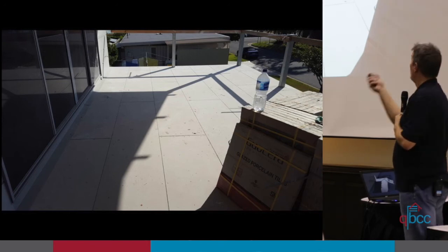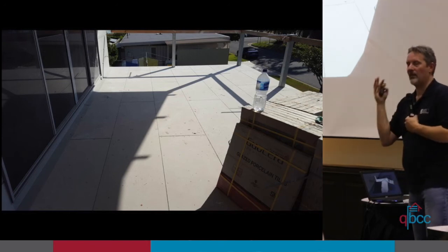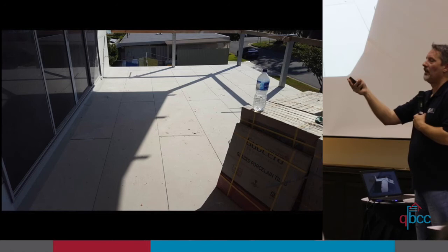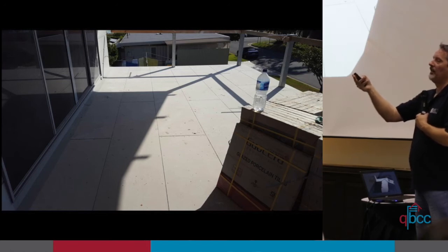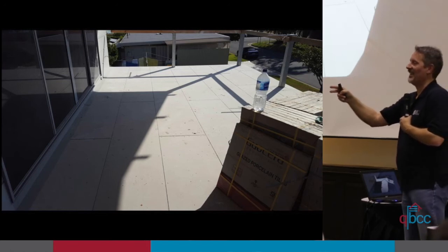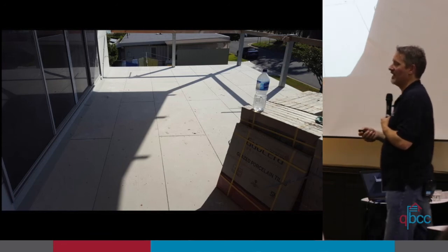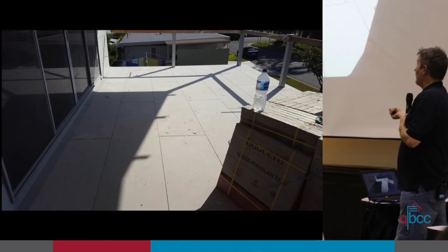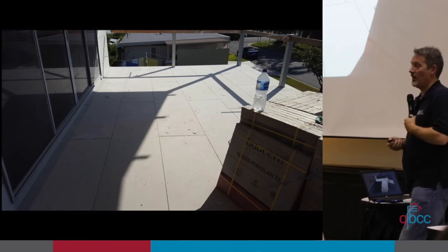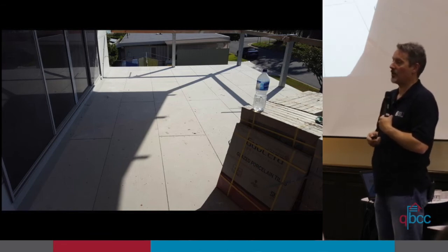The posts? Not what I'm getting at, but yeah, yes? No control joint for that length. You're almost there. The sheets are staggered. Their sheets are staggered, that's correct, right? So if you're going to put a membrane on this and direct fix tiles, you can't stagger the sheets.